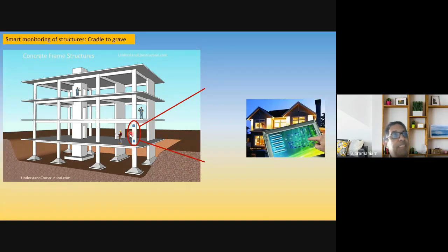Once concrete has gained sufficient strength, I have these listening posts inside concrete, which I can use for vibration monitoring, in any vibration monitoring scheme to infer the health of the structure. And finally, because these are not very expensive, I can distribute these sensors around the concrete and use them as arrays of actuators and receivers for ultrasonic stress wave measurements.